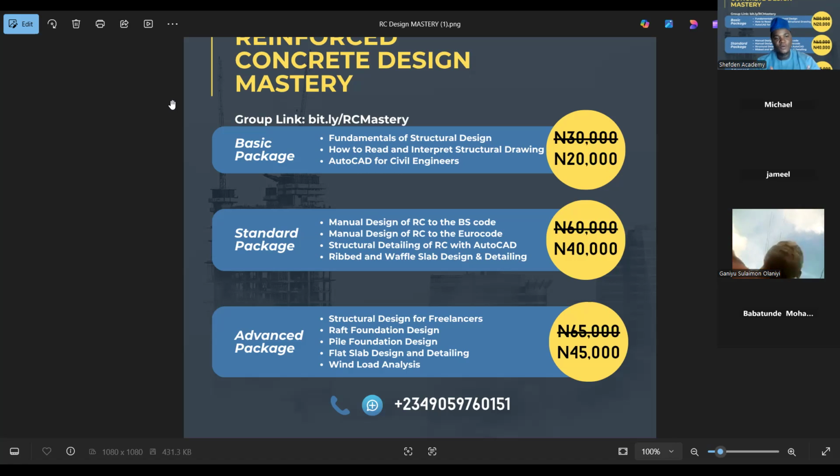Even though some of these members you might need to make adjustments. For example, the slab does not really include distribution bars, so you need to add them. For the columns, it's better if you can fine-tune it. The beams are almost perfect; you just have to adjust the scale and all of that. And the detailing for the foundation is also quite okay, even though generally we expect as engineers to adjust this detailing.